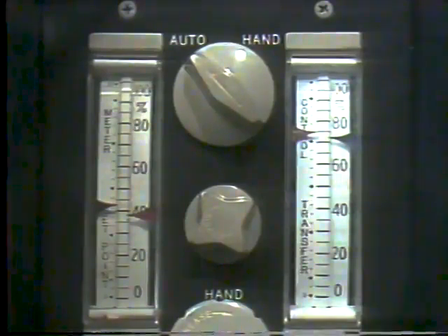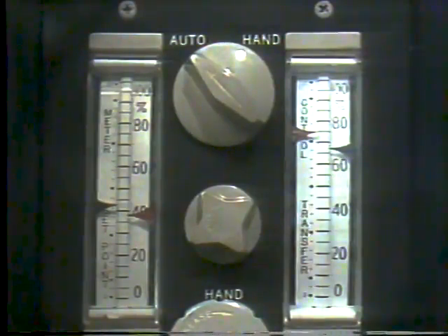You'll change set point with your controller in automatic, but you always put the controller in manual to make gain, reset, or rate adjustments. Once you've generated or simulated a load change, you'll observe the process reaction curve to see what effect the low gain had on the system.